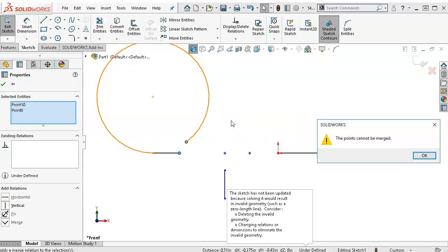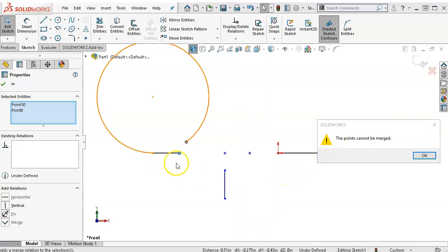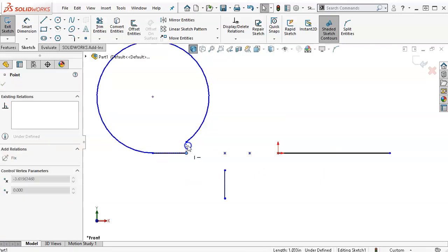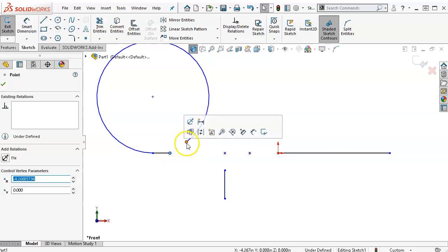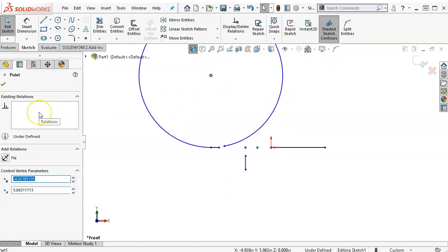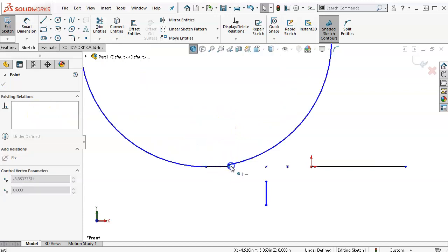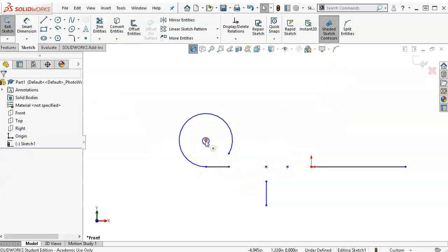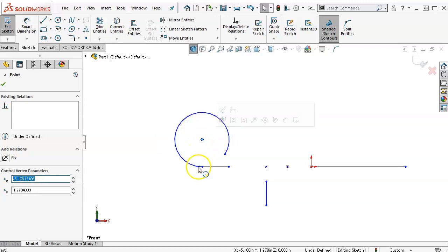Merged is one of those interesting items. And 0 length line. Well, it's trying to get rid of my line then. And I don't think the center point inferred anything, because we don't have a relation over here. So it's still trying to snap into a circle. Interesting. So, well, that makes sense. With the tangency coming off at a 90-degree arc, that point will be vertical unless I can shift it.